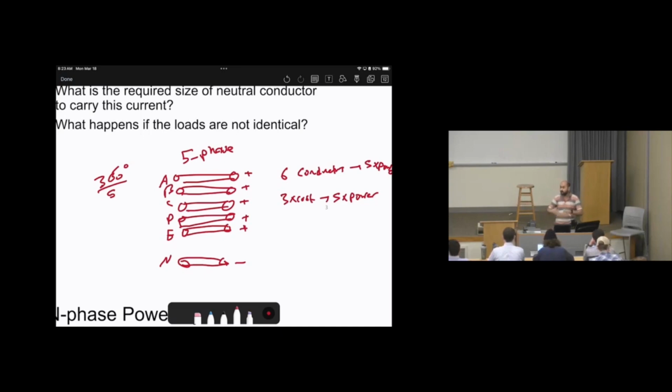This tower, if it is going to be larger and larger, this means the overhead cost in building that tower increases. You need more steel, you need more concrete on the bases, and these towers need a large thickness or a large capability of handling these loads. Some of you are mechanical engineers and you know about the loads more than me, how we can handle the weights, or the overall structure. So basically, when we have 5 phases, this requires a very expensive tower to build, way more expensive than the 3 phase.